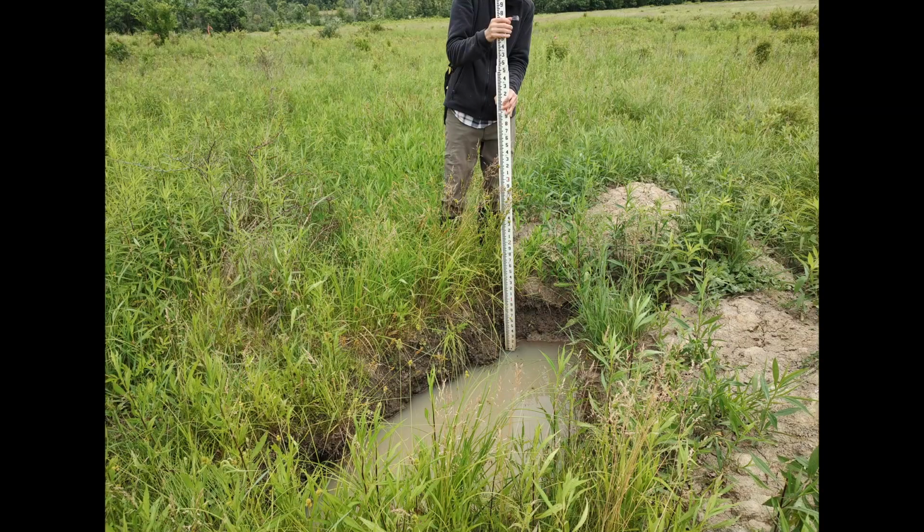Here's another site where it's not possible to build a groundwater dam. Groundwater has quickly filled the test hole. This shows it won't be possible to place clay in this hole and compact it to make a groundwater dam. The clay that's placed in the water will quickly turn to mud, and we just can't compact it.